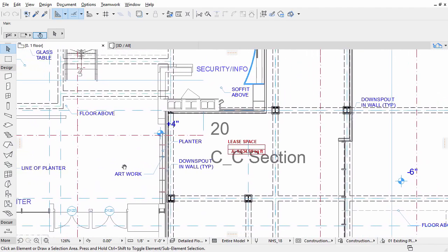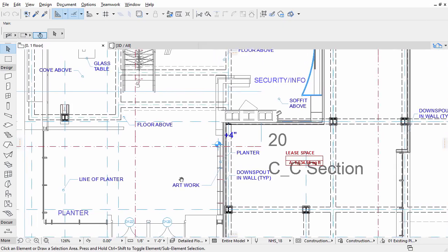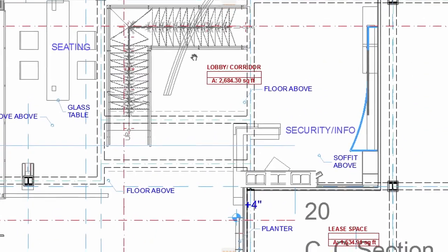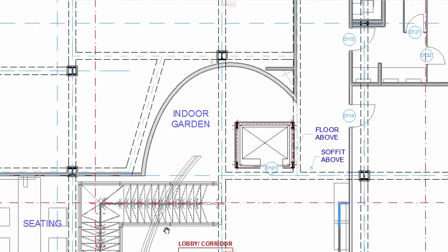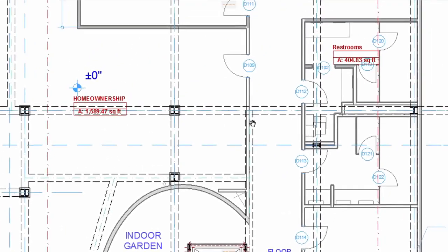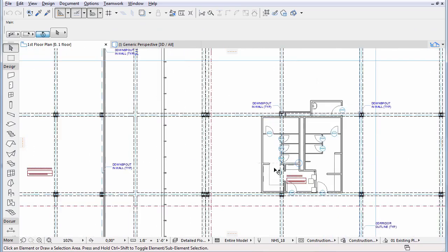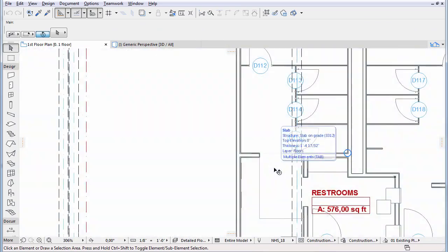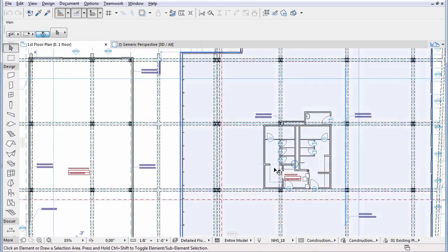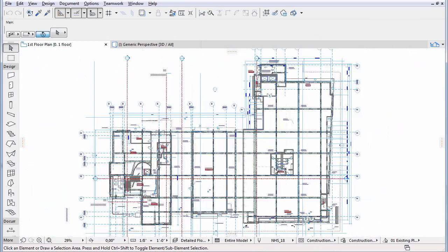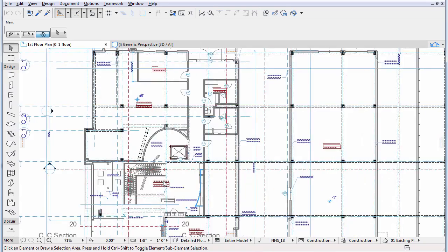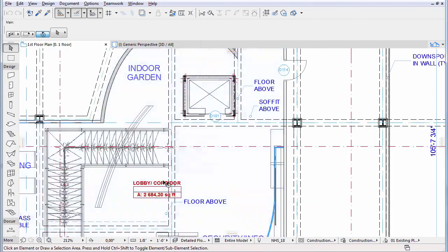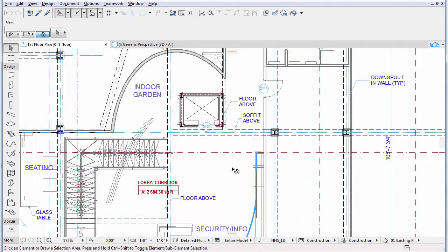There is an even faster way to navigate in all views. With the cursor in the main window, press the mouse scroll button to pan around the floor plan in real time. Remember to keep the scroll button pressed. Rolling the scroll button away from you will zoom in, and rolling it toward you will zoom out in real time. In these cases, the cursor position will act as the center point of the projection. This technique will let you move from one location of the floor plan to another very quickly. Try it.